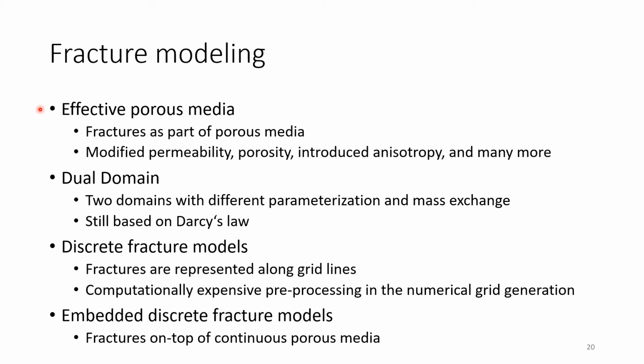We don't know their orientation maybe, or the fracture density, all those kinds of parameters we don't know. We don't care about, because we are operating on effective values. Right? You can introduce something like anisotropy, so that kind of gives you an idea about the orientation of fractures. You say, well, it's more flowing towards north-south than east-west, or things like this. You can introduce anisotropy in the effective parameters, so mainly hydraulic conductivity. But you don't have to, and only if you have the required information. And still, that doesn't mean I know exactly where individual fractures are.